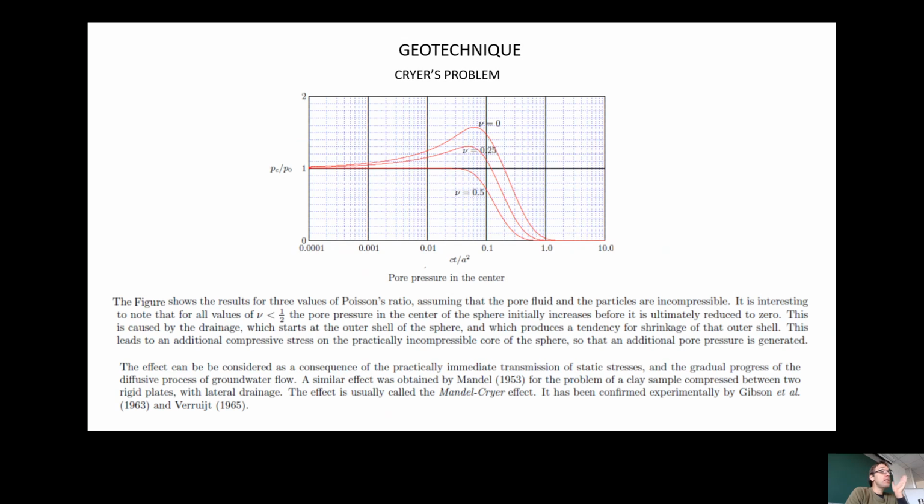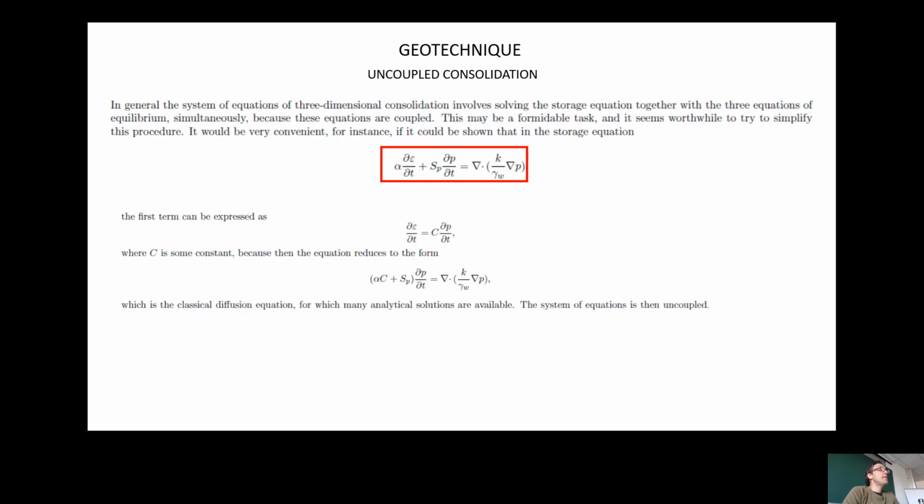It is important, otherwise, that if we consider again the general system of equations of the three-dimensional consolidation, the storage equation together with the three equations of equilibrium has to be solved together, and they are unfortunately coupled.